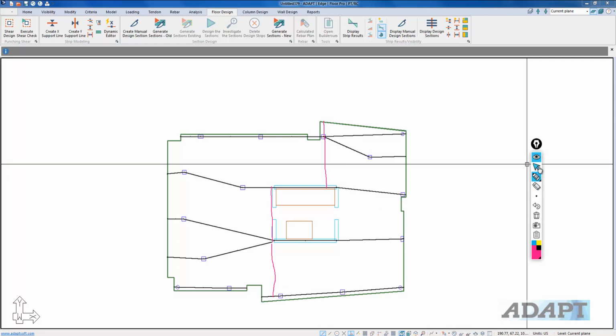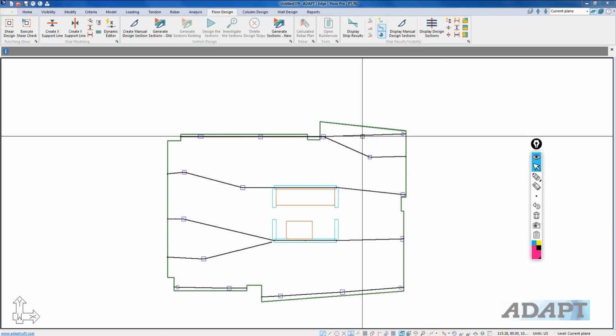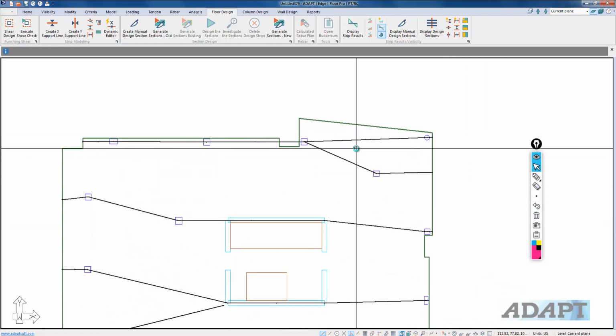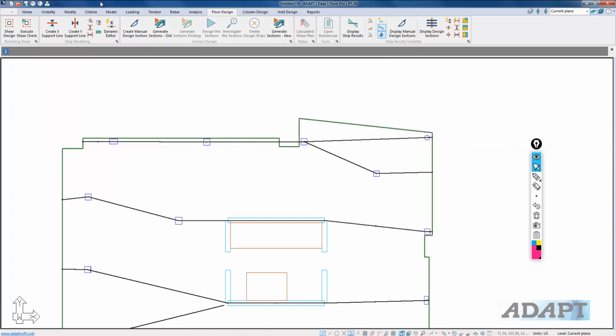We can also show the Y direction, and in the Y direction we would potentially have to have additional splitters. Splitters can become something that's very important and even time consuming to be able to generate proper strips. One thing that splitters can be used for is the ability to determine where you have a tributary cut off. I'll show you an example.